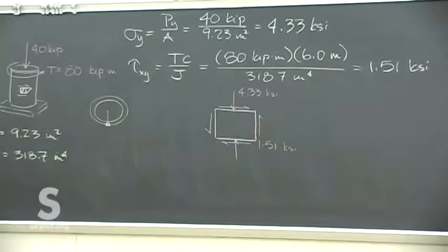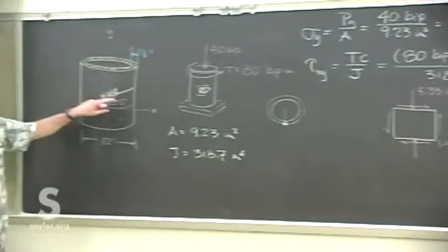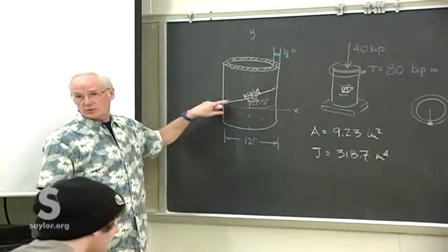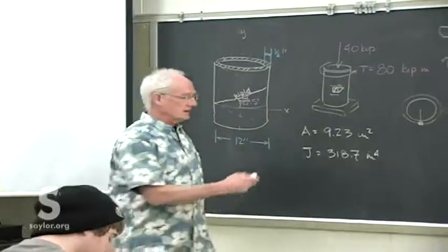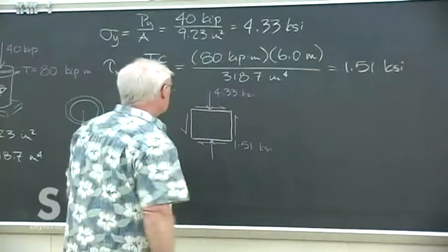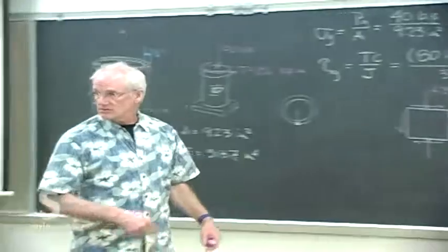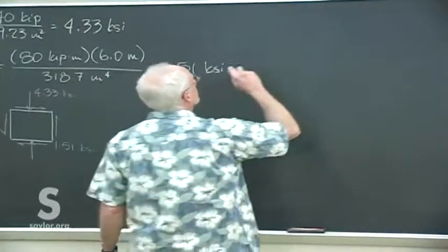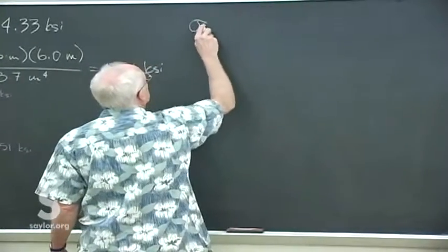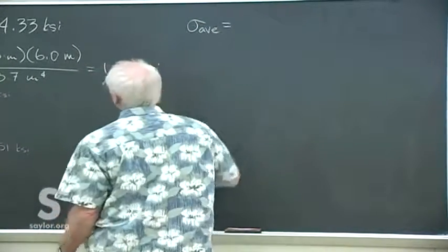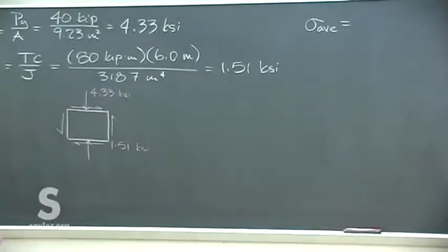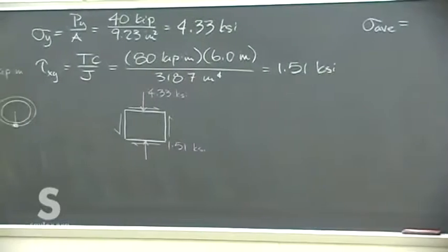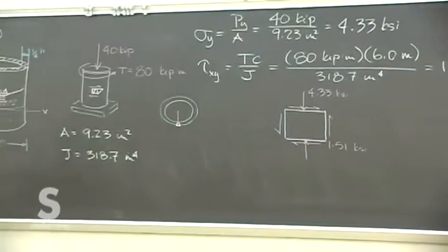All right. What we want to do, though, is look at what those become at this 22.5 degree angle where the weld exists. So probably the easiest way to do it is to just pull out those three equations and put in theta equals 22.5 degrees. So we need a couple pieces to go in there. The average normal stress is, you calculate it for me.